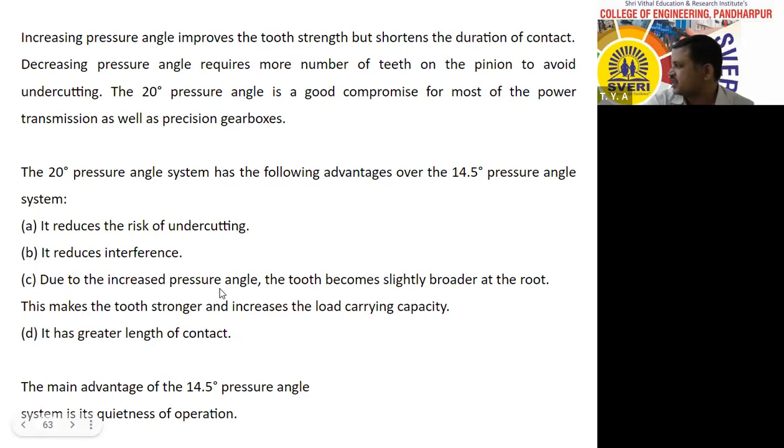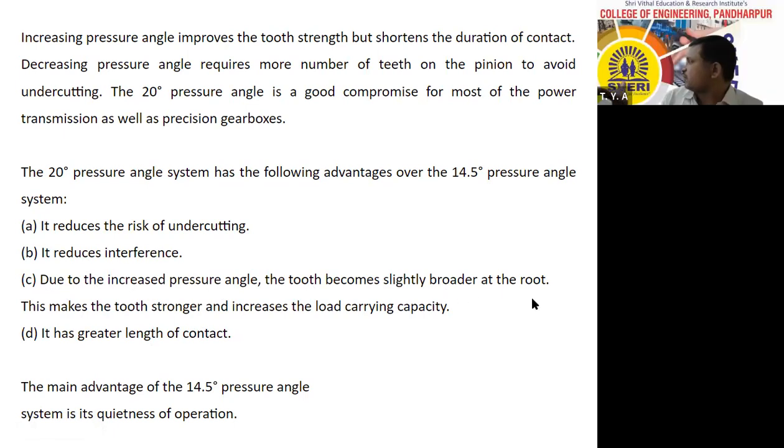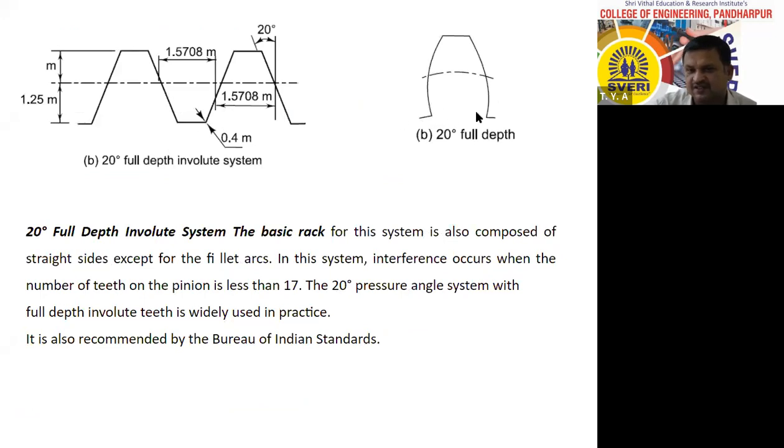Due to the increased pressure angle, the tooth becomes slightly broader at the base. This is the base portion, at the root. This makes the tooth stronger and increases the load carrying capacity. Look, for 14.5 degrees, if you measure this much distance at the base, this distance is smaller than this distance.